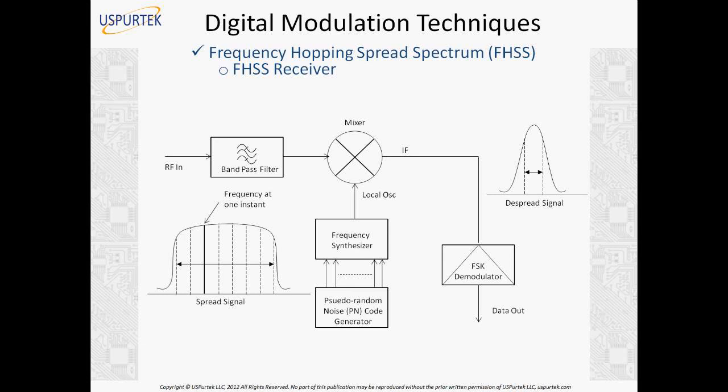Well, the PN code is just a random code used to create the local frequency. But what decides the bandwidth is how many times we hop the frequency. So how wide is our band? What is the range of frequencies we are hopping? That is what decides the bandwidth. So the PN code itself is just a random code used to hop from one frequency to another, but how many frequencies you actually hop decides the bandwidth.